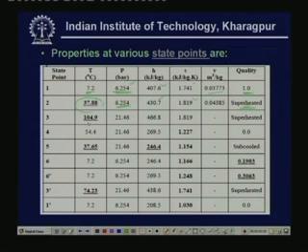And point 3 is the exit condition of the compressor. So, what do we know at this point? We know the pressure, because this is nothing but the saturation pressure at 54.4 degrees centigrade, and we also know the entropy, because this is an isentropic process. So, S3 is equal to S2. From the known values of pressure and entropy we find the other properties like enthalpy and temperature. The temperature works out to be 104.9 and the enthalpy is found to be 466.8 kilojoule per kg.